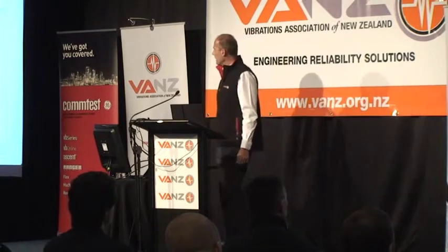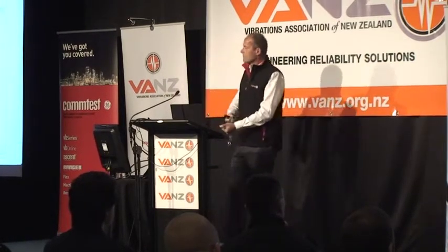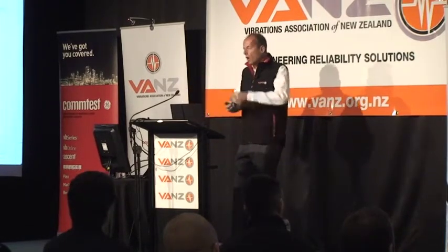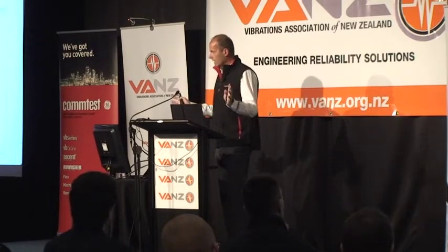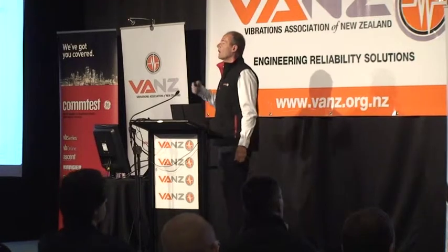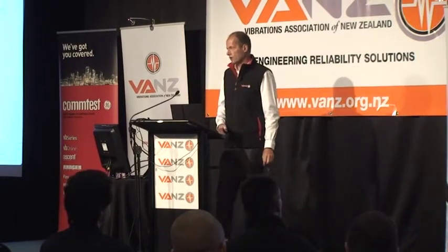I mentioned lubrication. Well, you can listen while you lubricate. As you're pumping the grease in, you can hear what effect that's having, hopefully pushing those surfaces apart. That's all great. Mind you, if you ever listen to the bearing and it sounds awful, that means you're not lubricating it properly, because it should never sound awful. But anyway, there's a lot we can do with all of these different condition monitoring technologies.